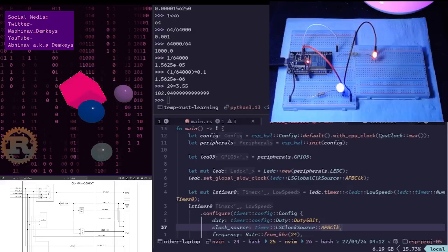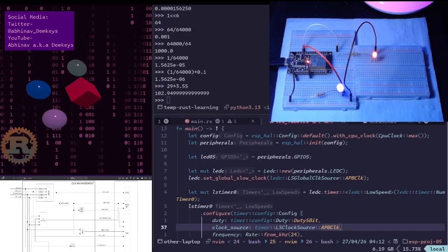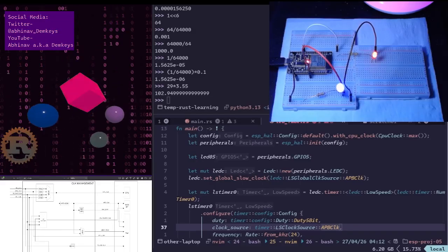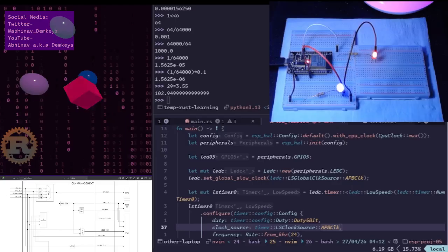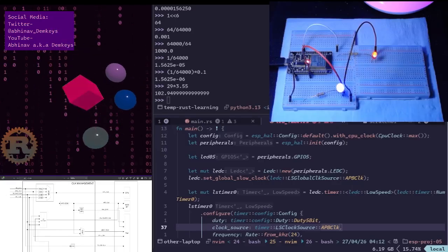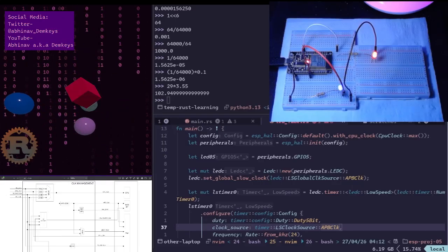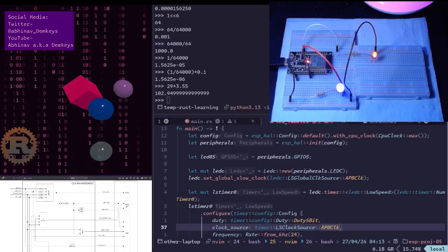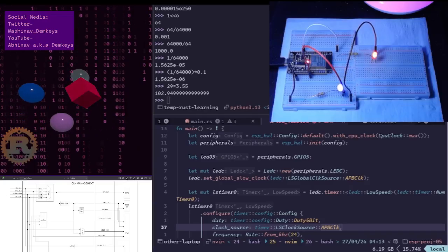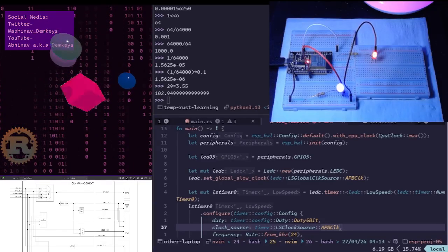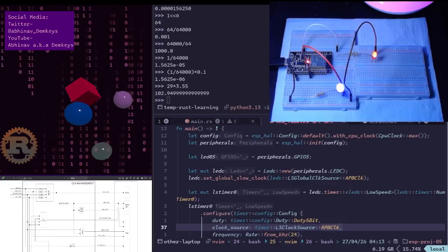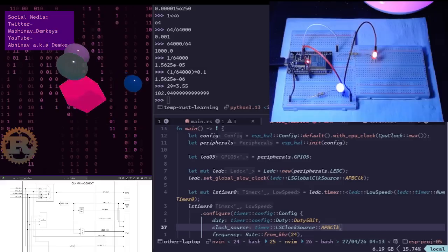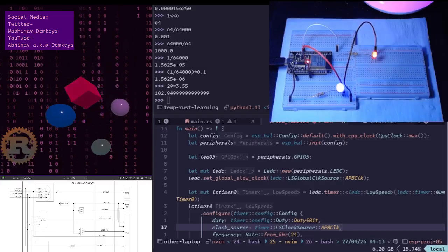So there's division happening, definitely, for sure. But where exactly is that clock signal coming from? Is it coming from the CPU hardware, where it would be based on the CPU clock? Or is it coming from the PLL hardware, where it would be based on the PLL clock, and the division would happen accordingly? Now, in another conversation that I had with Gemini, it mentioned that it's derived directly from the CPU clock.